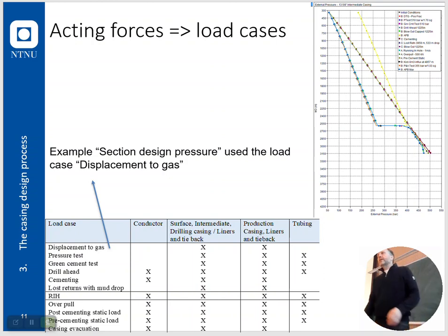You typically talk about deterioration of the mud. After approximately a month, in casing design, we say that the mud is completely deteriorated. So in the top it will be water, in the bottom it's completely sagged out.